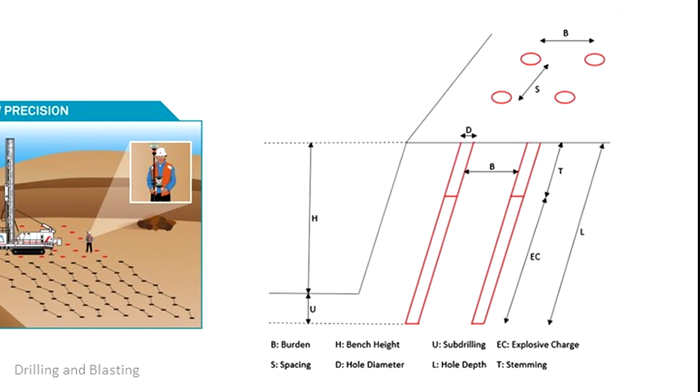Here are a few definitions used in the terminology of quarries when referring to drilling and blasting. Notice that in most cement companies, the quarry face is always at an angle, never vertical. This is of course for safety reasons to avoid sudden collapse of the top bench when machines and people are preparing for drilling. The maximum bench height, H, is normally limited by safety governmental offices. In many countries, say in Europe, this is limited to 12 meters.